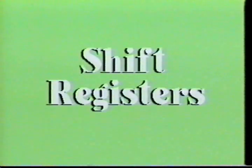Registers are nothing more than a storage unit used to temporarily hold information until the information is needed. The most common storage register is the shift register. There are several different circuit configurations that are called shift registers. They are classified by the method by which data inputs and outputs to and from the register. For example, shift registers may be classified as serial in, serial out; serial in, parallel out; parallel in, parallel out; and parallel in, serial out. As you can see, the shift register can convert data from serial to parallel or from parallel to serial.